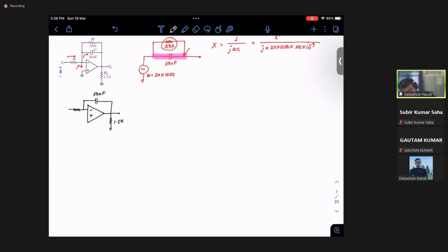This is your R, and this is the input signal you are playing, and this is your V, right? So how will I solve this circuit? I will just simply use KCL in this branch. Let's say this is I1, this is IC. So your I1 is nothing but V input minus 0, this point is 0, over R, is equal to, what is this current?